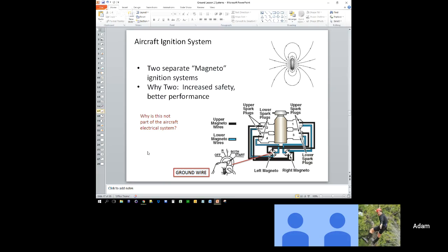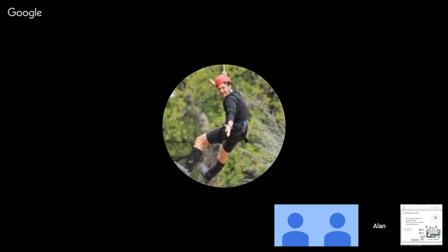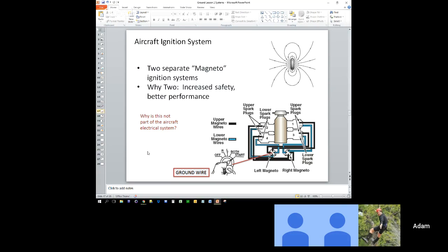Now, your question being, why would you even give someone the option? And what's the difference between both and start? Are those in flight versus engine start? So similar to your car, the start position is all the way turned where you're engaging your starter, and the both position is when you let go of the key and it kicks back. Got it. Yep.